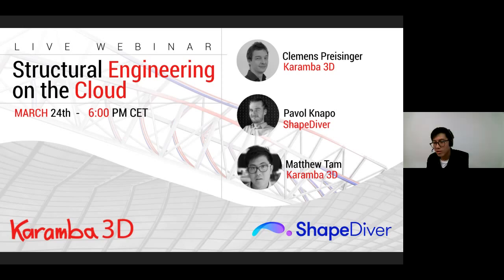There was a question in regards to, we have already answered this, but can I upload any Grasshopper to Karamba definition to ShapeDiver? So Karamba is now supported with the 1.33 version on ShapeDiver. As you saw, I tried to upload a script which had some components with the 2.0 version of Karamba, and it failed. And this is because plugins need to be, for example, first activated and also confirmed on ShapeDiver's side before they are freely available to use. But everything that you can find in the 1.33 version of Karamba can be uploaded on ShapeDiver.